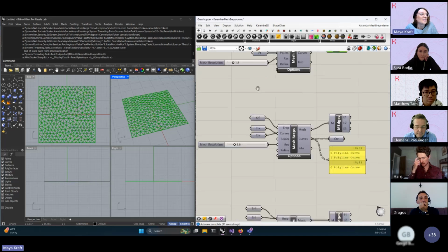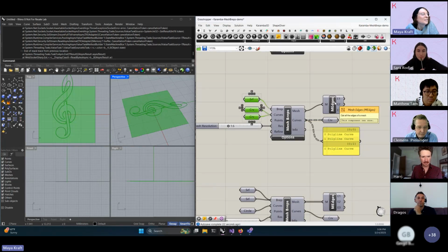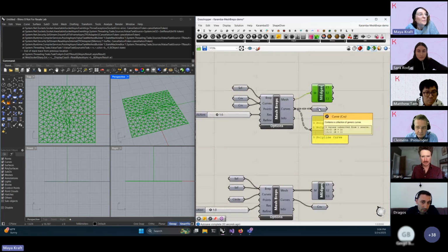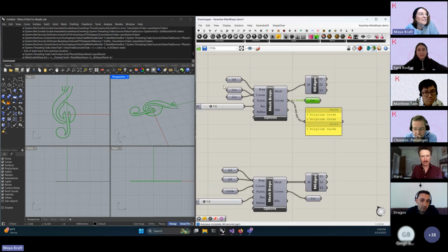If you would like to maintain the connections between them, that's where these curve inputs will be useful. As you see here, with the surface and curves, the curves can pop out of the surface, but the connections between the vertices are maintained as edges in the final mesh. Not only that, but we also provide your input curves as they ended up in the mesh, provided here as polylines. The paths are maintained. Curve 1, 2 shows up as path 0, path 1.